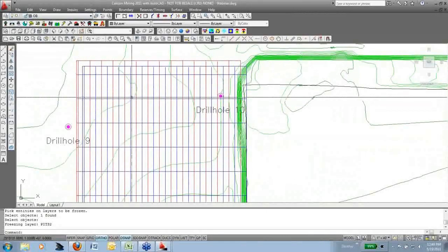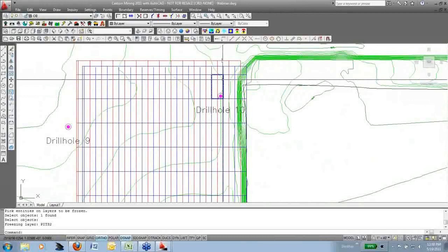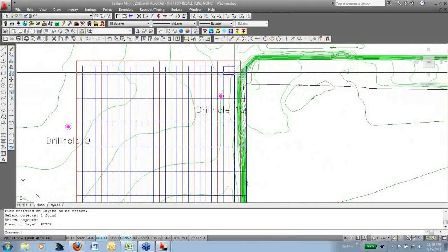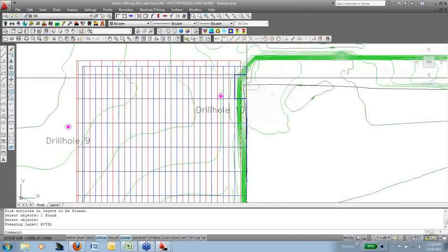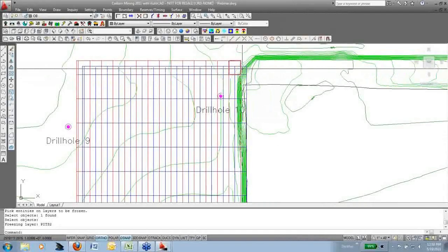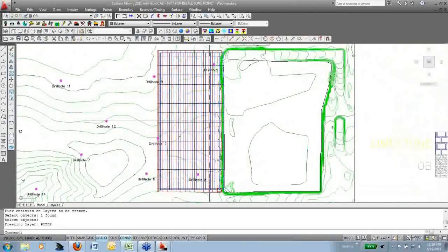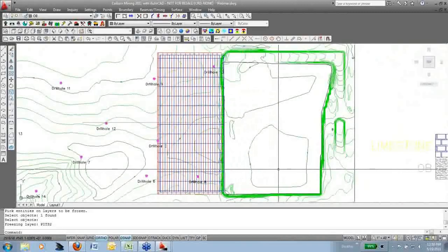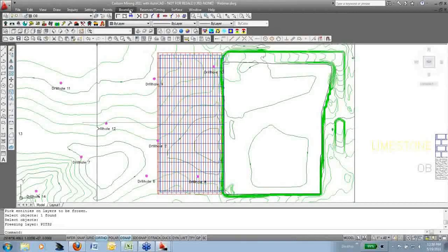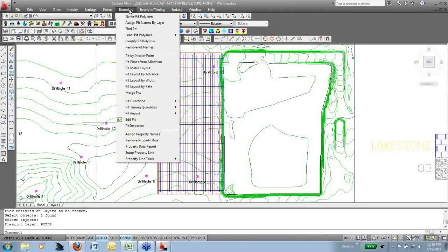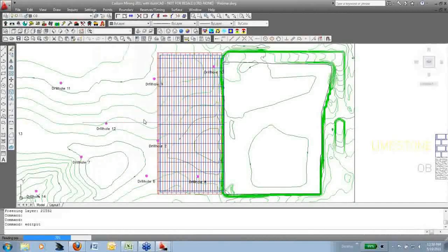And these are 50 by 100 size blocks, and they are offset. Here's your bench 2, which comes down from this pit floor and extends a little further out on that east side. So this is a nice, clever way to lay out your pits in different pit line work by bench. And these should have volumes already assigned just by surface mine reserves. And so we'll confirm that with boundary edit pit.